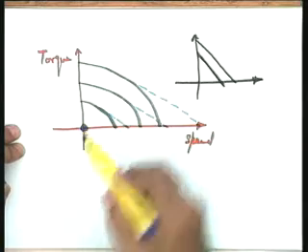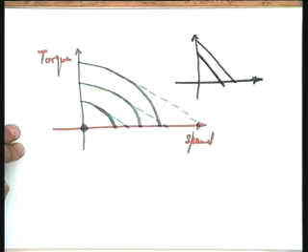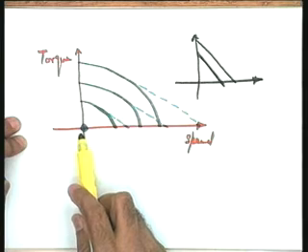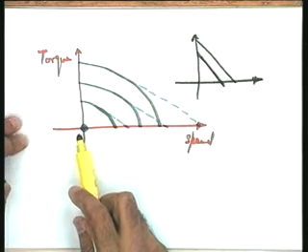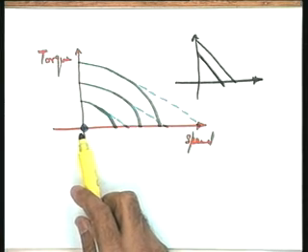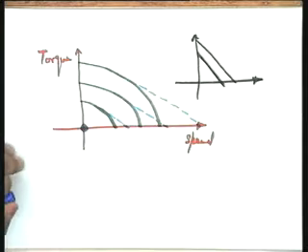You see, when I am writing a linear model, the linear model is not valid for the entire region of operation. The linear model is valid under the assumption that this is my operating point, which is speed equal to 0, and around this operating point the curves are linear. And therefore, I am going to use AC motor as a linear device throughout my discussion under the assumption of this being the equilibrium point, and which is 100% true as far as position control systems are concerned. Okay? So if that is the case, what is the torque?